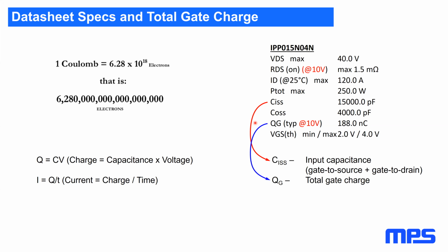Next, with this information, can we say that MOSFETs can be used as a switch for switching between two power sources? Sure, you can, but you have to be cognizant of the body diode. Quite often when we're using MOSFETs to switch power, you'll see two MOSFETs in series in opposite directions. Maybe you connect the two drains together and the two source terminals are the input and output.